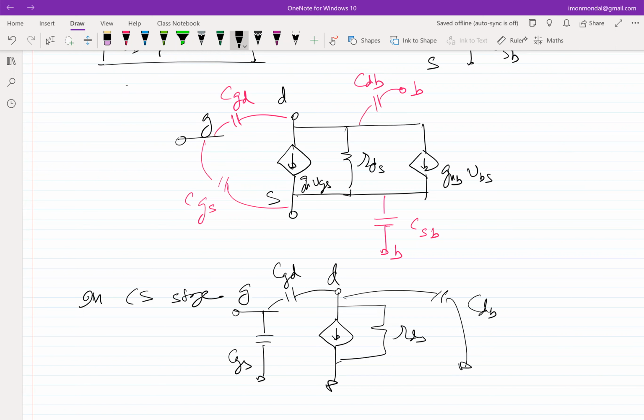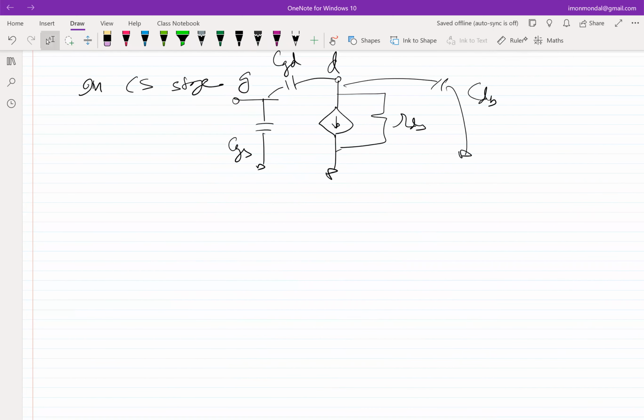But the key thing that I want to focus on here is the following. The effect of this capacitance is this: this GM, however you have realized it, doesn't really matter. It's a differential amplifier or a common source amplifier. This GM will have a capacitance at this node, RO. Let me call this C1. This C1 is probably a combination capacitance of whatever is connected to that node, right? So let's assume that is C1.